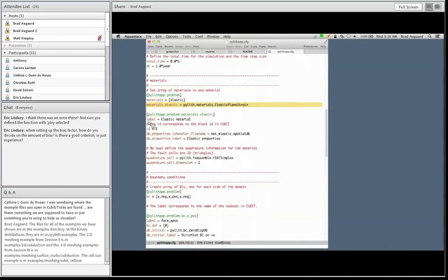For boundary conditions, very simple default boundary conditions. We're going to use the zero displacement database to specify zero displacement on the boundaries. So we constrain the displacement degree of freedom perpendicular to the boundary. So on the x positive face, for x positive displacement boundary, we use the node set face x pos.